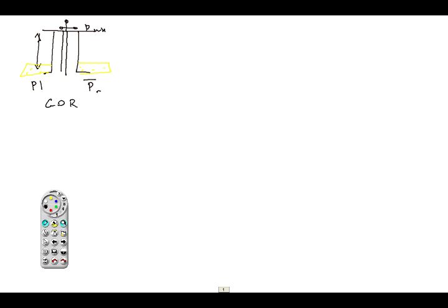Right. So if I choose bottom hole as a node of interest, then what I can say is this: my operating rate for this well will be such a rate that my bottom hole pressure inflow is equal to my bottom hole pressure outflow.